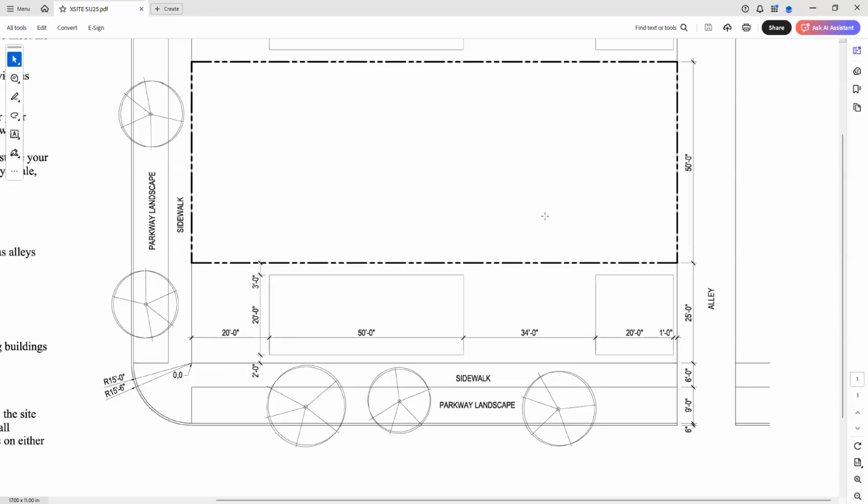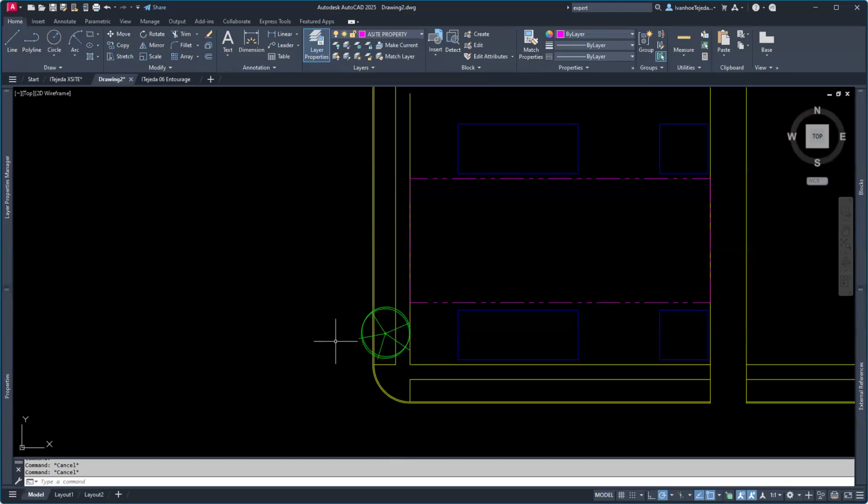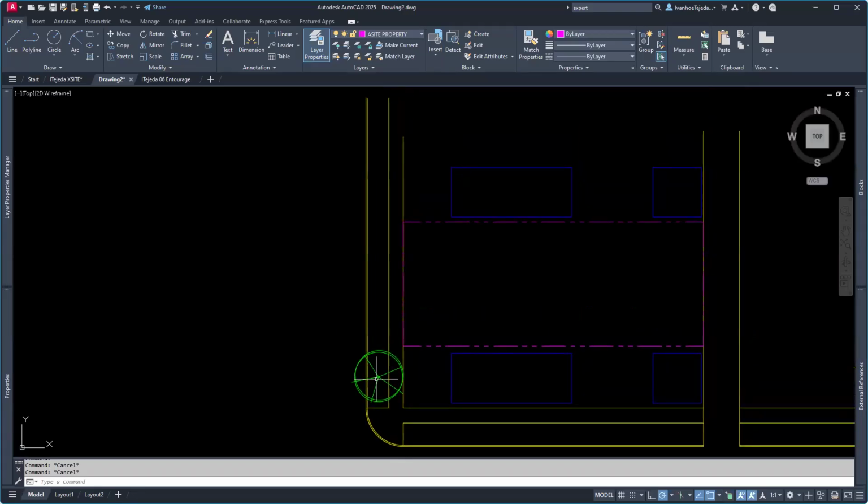We haven't touched the site yet. When we do, we can start adding trees there. And you'll see that they're different sizes and they're also oriented differently, but it's the same block. Let me show you what I did. Going back to my example, there's the tree. And let's say I take this tree, I'm going to select it, and then I'm going to type CP to copy it, enter. And I just want to copy it in this direction, at least 25 feet or so, 20 to 25 feet. Or more if you want, but I'll type in 25 feet, enter. And if you want, drop another tree. Let's say this one is 50 feet away.